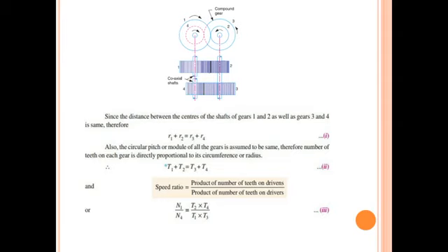But the difference is what? In a reverted gear train, input and output shafts are coaxial. Applications for this reverted gear train are the lathe back gear, industrial speed reducers, automobile transmissions, and clocks.